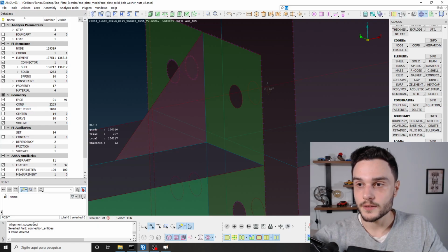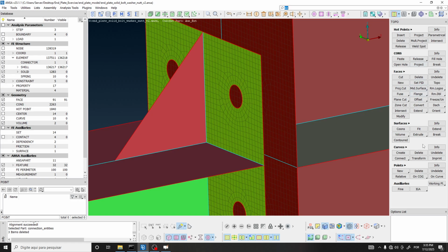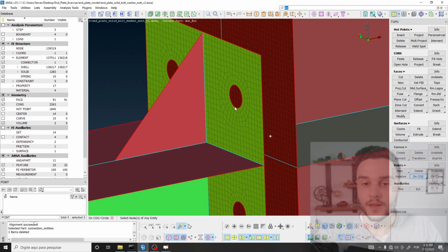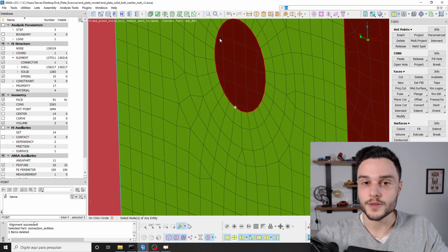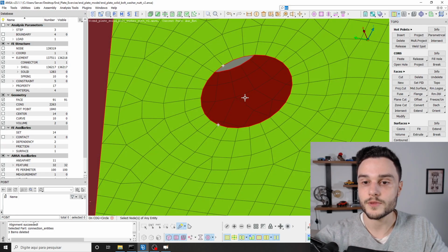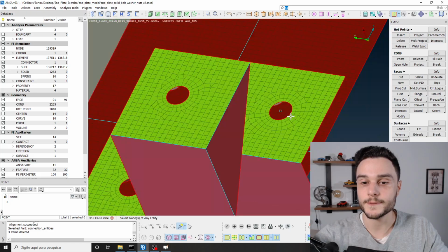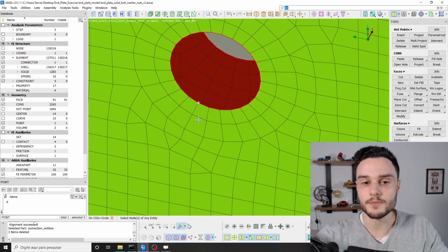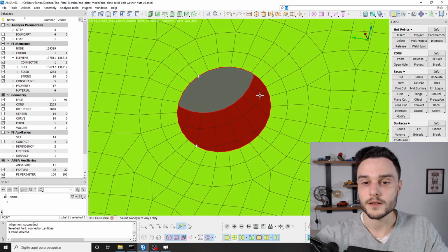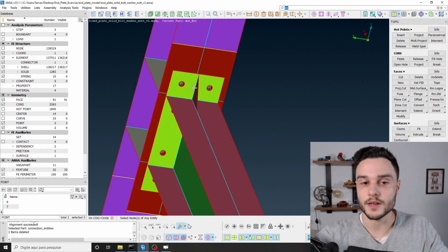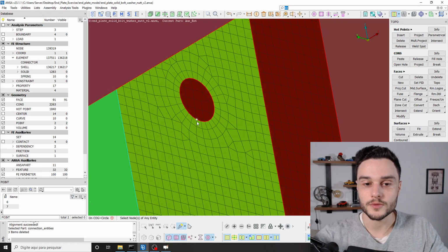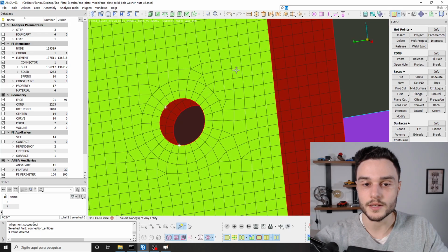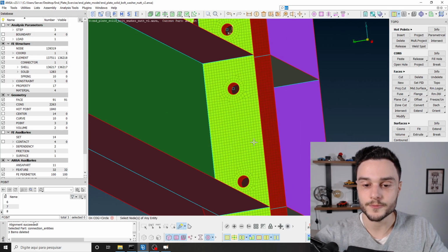And then go to classic topo module, and then again use the arc circle tool, and then select 3 points from this circle, middle mouse button. Here we have the first reference point, and let's do the same thing for all these circles. So here we have the second. Just be careful so that you correctly select the nodes.